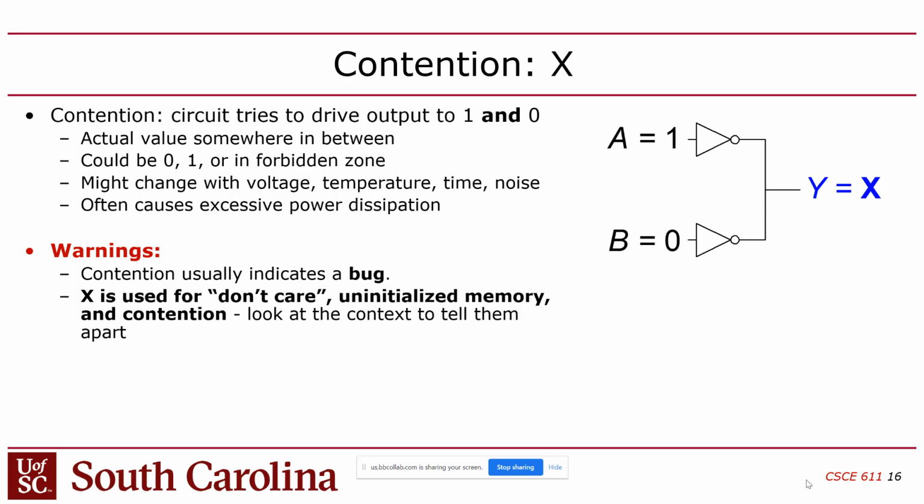So this is showing what can happen if you had, for example, two statements in your code that both try to set the same wire. Now I call this a wire. It's a net in the sense of a circuit design, and it's a voltage potential inside your design. But inside your SystemVerilog, it looks like a variable, and it's very easy, obviously, to double assign a variable. I mean, you guys do it all the time. In a normal programming language, unless you're doing single static assignment, it's very common to assign a variable twice on two different lines of code, but if you do that in Verilog, it's bad.